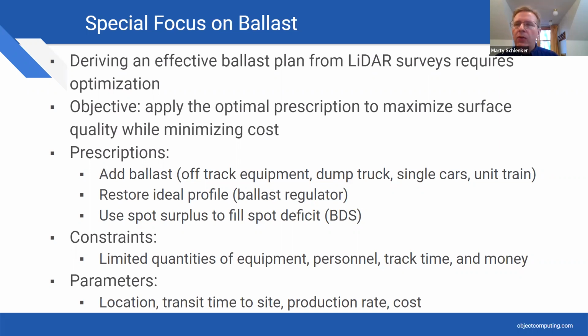And so when you apply your LIDAR survey and you measure the ballast section in 3 dimensions, one of the things that you find, as you take cross-sectional areas and compare them against the ideal profile, is that you will have areas where the ballast has subsided or fallen away from a supportive position in the subgrade. Okay, and so ballast needs to be replaced.